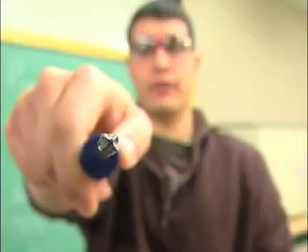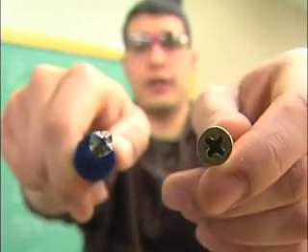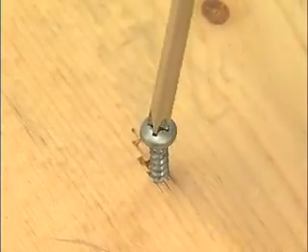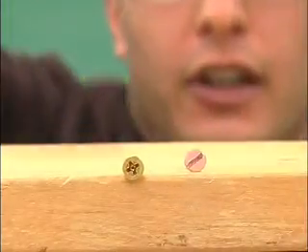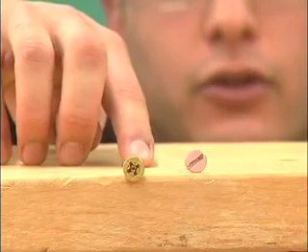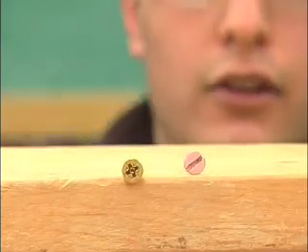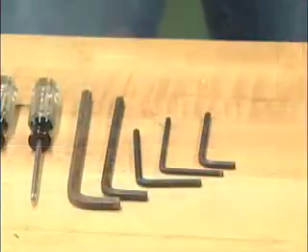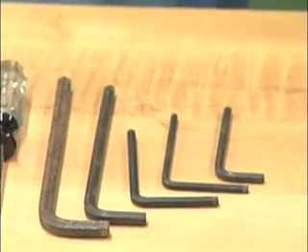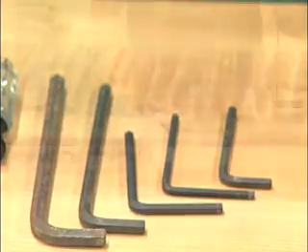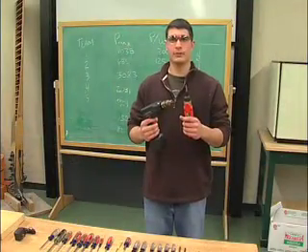The Phillips head screwdriver is designed to be used with screws with an X-shaped slot. Again, the closer the match, the easier it is to tighten the screw. Which screw to use? The Phillips head screw is designed for the application of extra torque, so it provides a tighter fit. Use it when tightness is critical. The Allen key or Allen wrench, a hexagon-shaped screwdriver, is often used to put together furniture. It's often L-shaped.